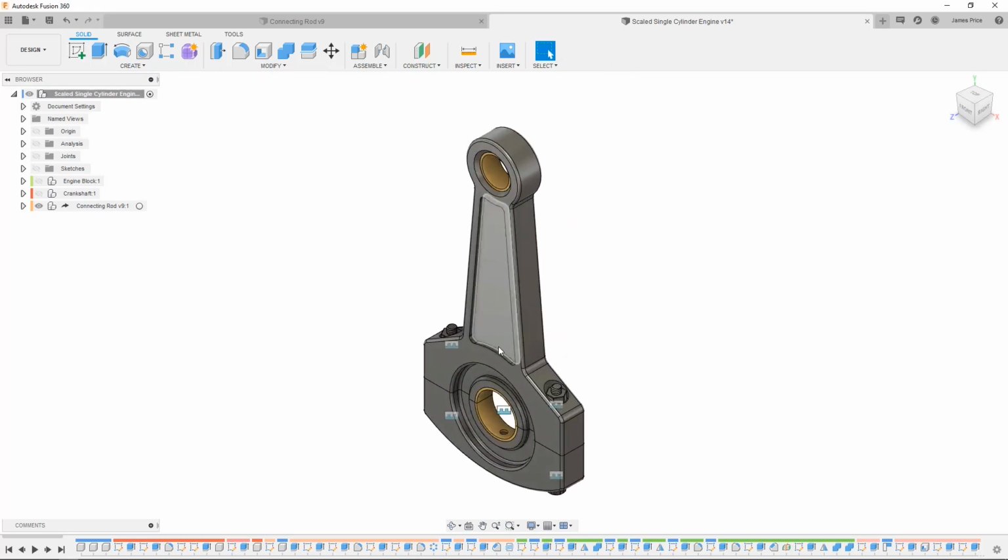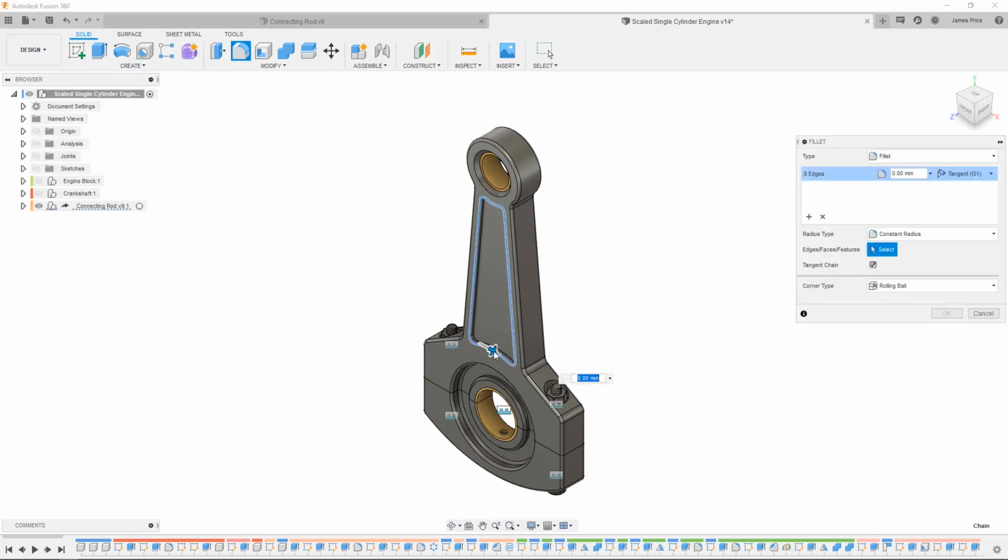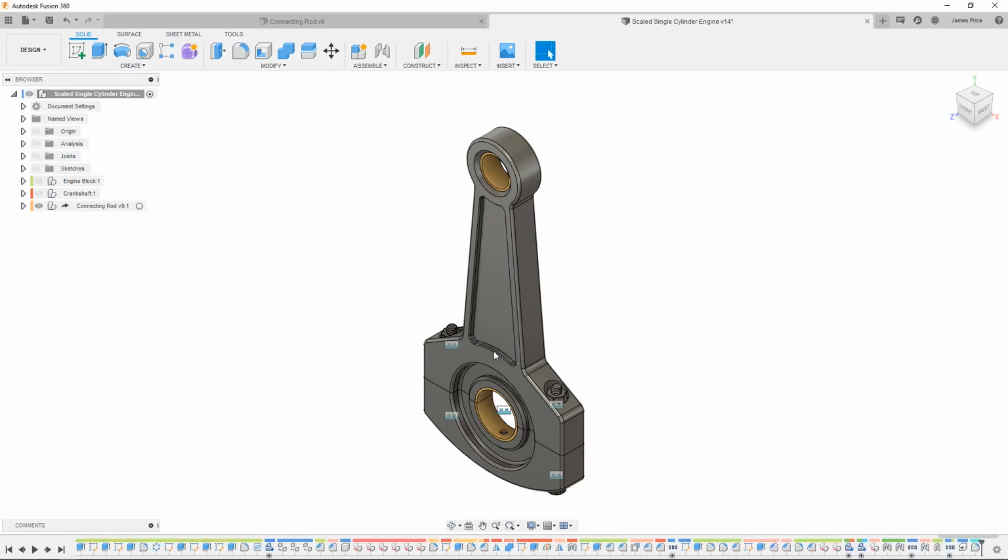With derived components, you can amend these as you would with any other component, although any changes will only be reflected within that specific assembly and won't affect the original, with the edits captured in the timeline. If you want the changes to be reflected across all instances, then you'll need to edit the original design as you would with a copied instance.